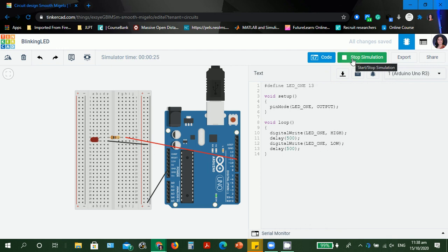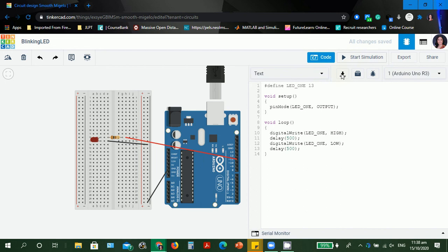Okay, so actually those are the problems with electronic component setup and the Arduino sketch. So you have to be very careful. You must remember where you assigned these electronic components, to what pin you assigned them, so that you will have no problem. And as an advice from experience, it's easier to edit the Arduino sketch than to change the connections.